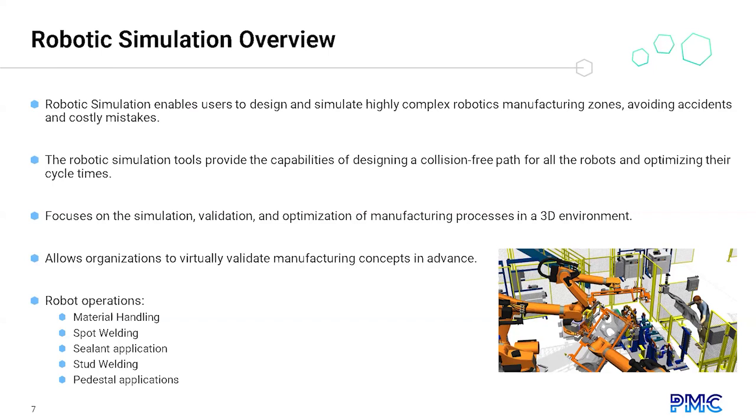We can check for possible mechanical interferences and also optimize the robot cycle time. It is mainly used in the pre-planning phases of a project, where everything can be tested and validated within a controlled environment. So problems can be detected in advance without impacting the real environment, and problems with new installations are avoided.